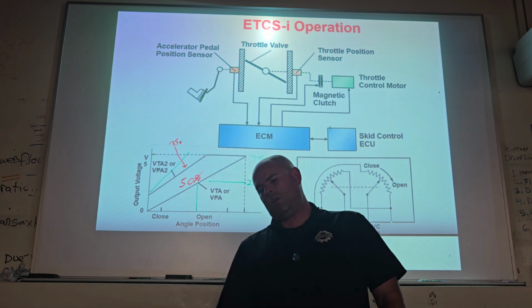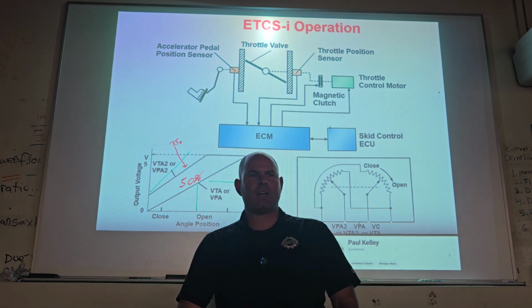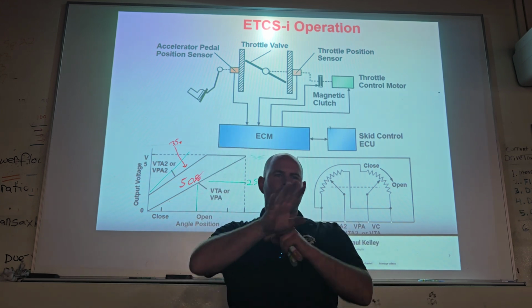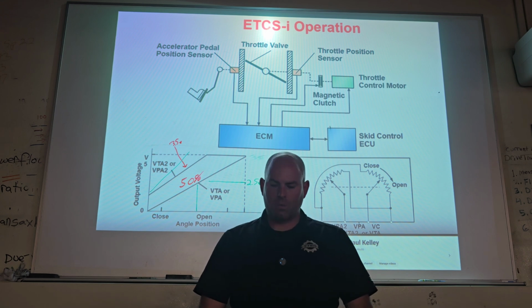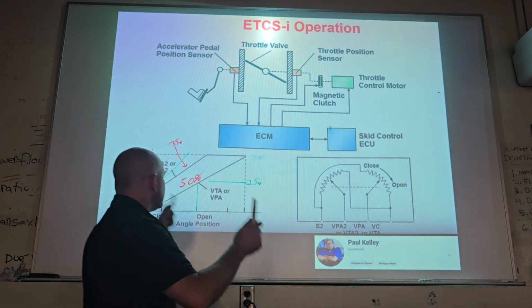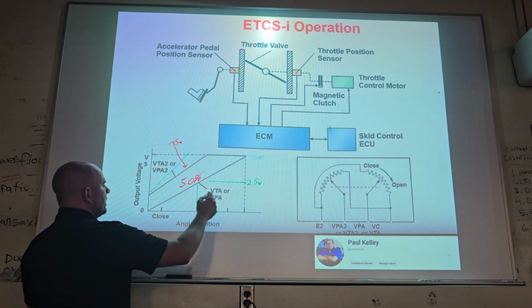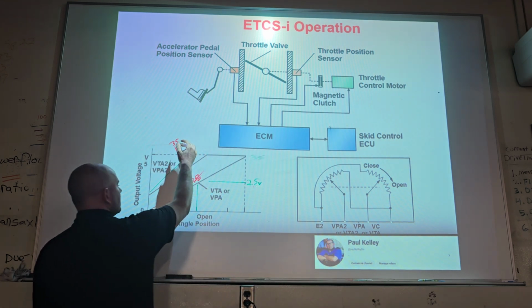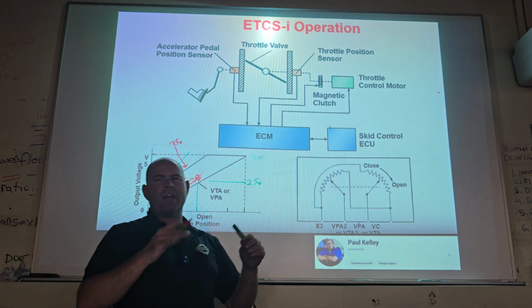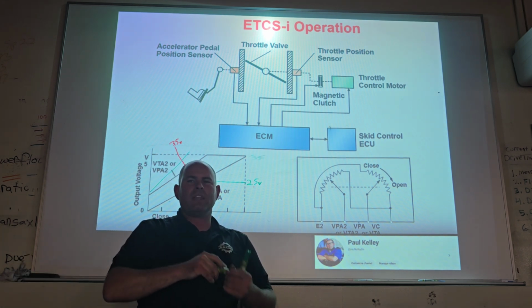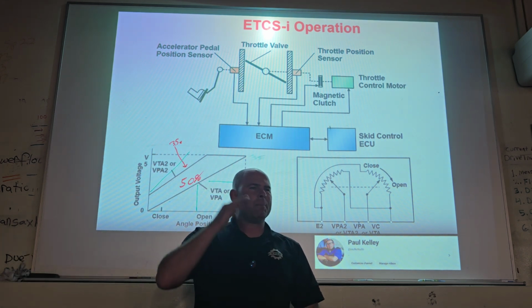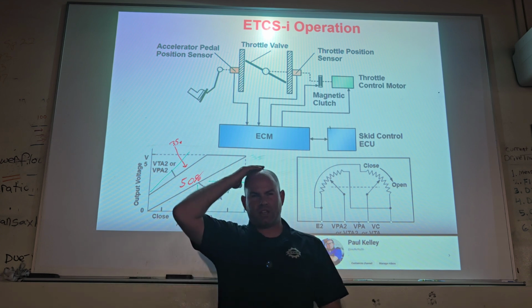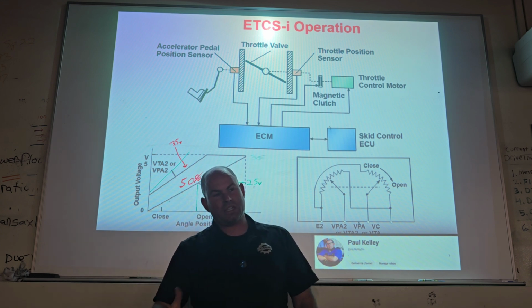and I look down there, I'm like, oh. I pull the floor mat back, and the throttle goes whack. The pedal goes wham. I'm like, wow, this is a legitimate complaint. I could hardly believe it. But thinking about it, what is the likeliness of this thing reading 2.5 and this thing reading 3.5 randomly? Where did those voltages come from? They have to correlate perfectly. I'm thinking in my mind, there's no way there's an electrical fault. I immediately look, is this pedal stuck?